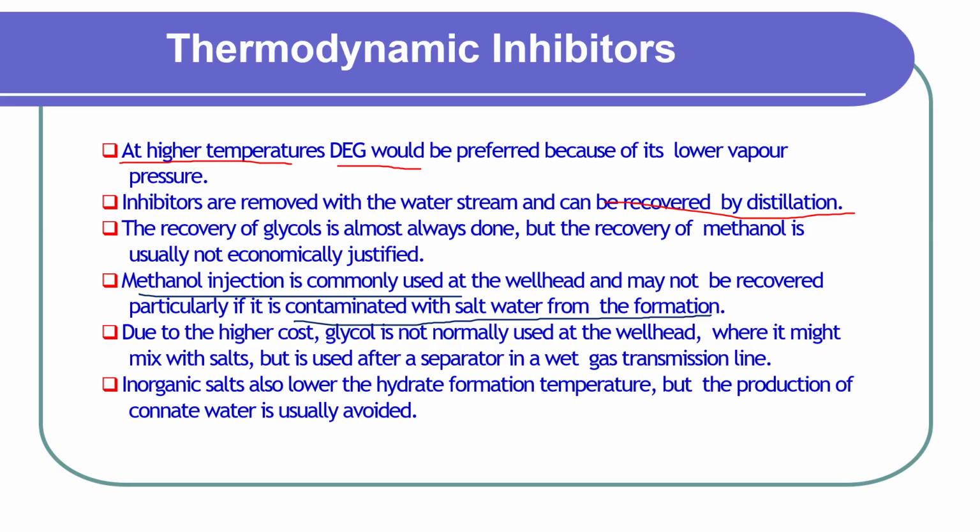While if you are injecting after the wellhead, for example after the separator, where you have a wet gas line, then it's recommended to inject glycol, despite the fact that glycol is more expensive than methanol. The fact that you can recover the glycol is good enough to justify injecting glycol in this scenario.